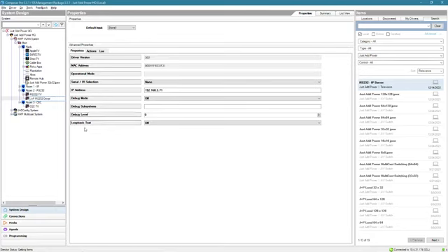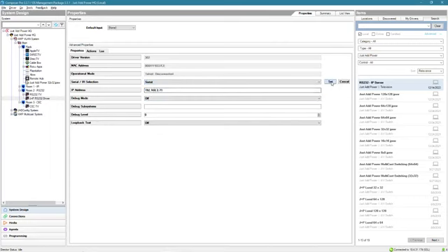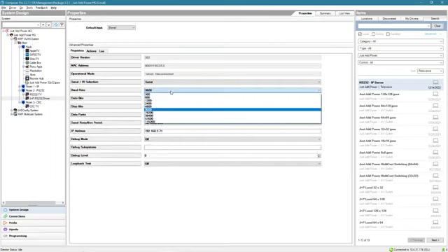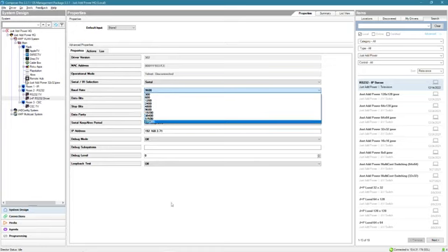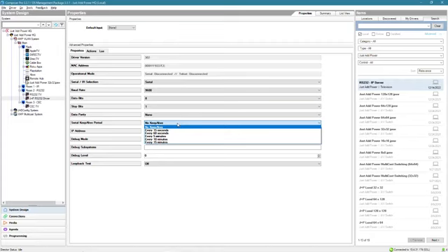And we've got to do two things in the property windows to configure this. We have to set our serial IR selection to serial because we're doing serial. Then we're going to set our baud rate to match the baud rate of the television. Now, most televisions are going to be 9600, 8, 1, and none, or 8 and 1, depending on the order. Does it need a keep alive, meaning something to make sure that the TV doesn't fall asleep? You can set that however you'd like.